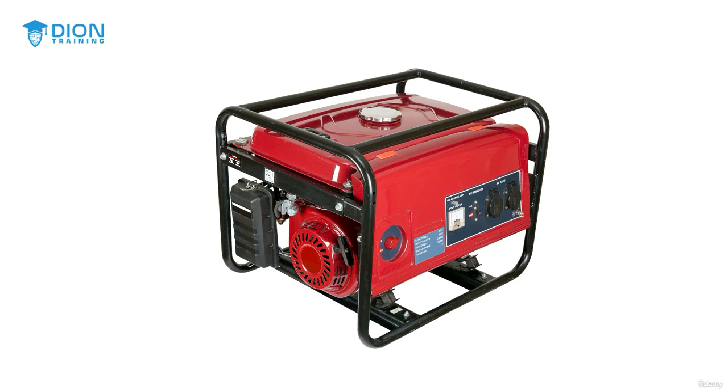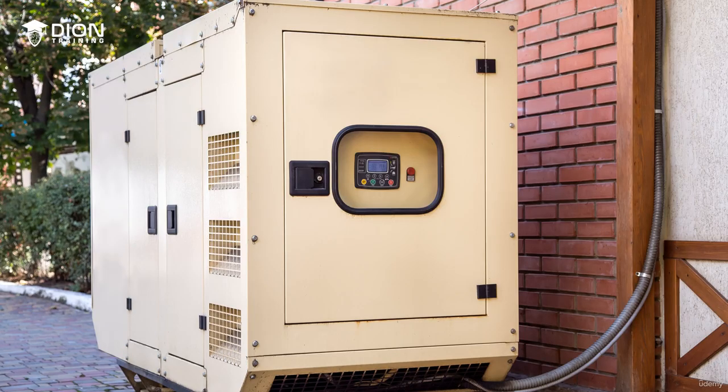So, if you have a larger workload power need, you can use a permanently installed generator instead. These permanently installed generators usually make up the backbone of your data center's emergency power architecture. They rely on either diesel fuel, propane, or other types of natural gas to operate, and these generators tend to be very large and they can power an entire building during a complete power loss event for hours, days, or even weeks at a time, depending on how much fuel your system has in its reserve tanks.